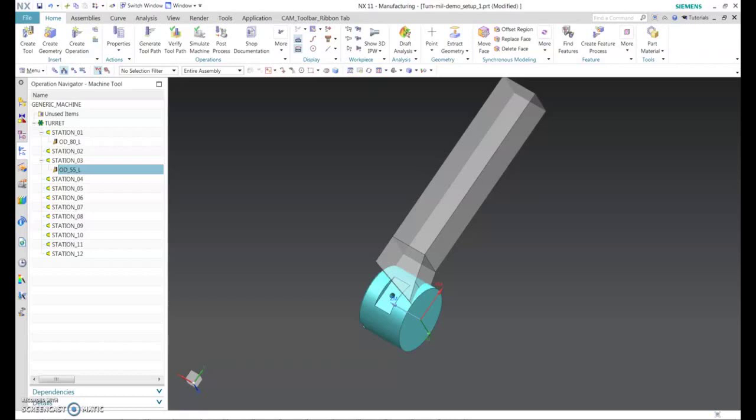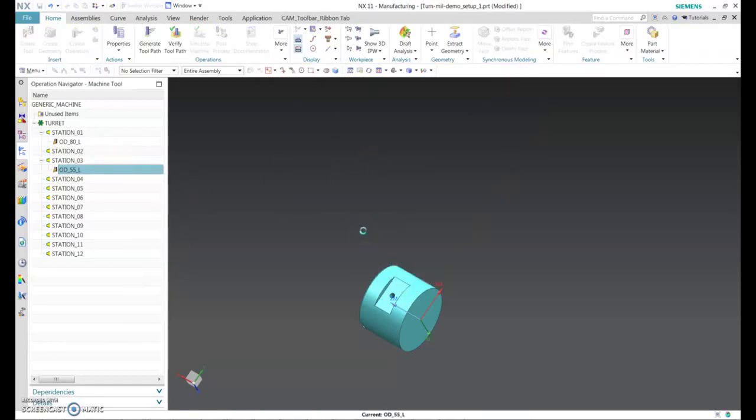Once you go, like I told you, to the manufacturing tab and pick up the MILLTURN Express, I will put in all the models that you need to simulate the toolpath, along with the tutorials, in the link given in the tutorial. The framework is established now. If you want to change the clearance angle or the geometry of the tool, go and right click, edit.